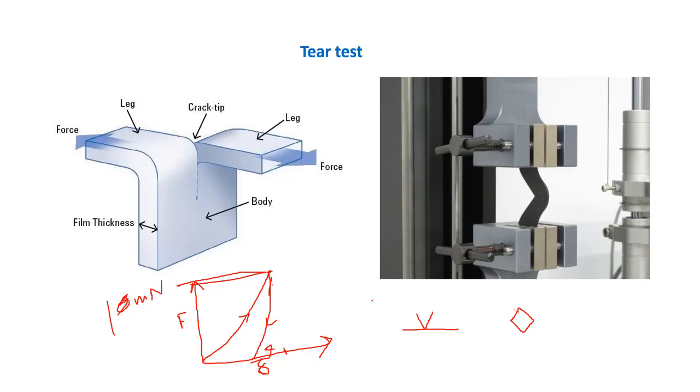It will give me a hardness value, but from this curve I can also get the yield stress and the elastic modulus. So it is related at some point, and we can do that for polymers also. I think you can get the yield stress for polymers using this. Maybe this is the only way. I'm not sure, but with this, we can definitely get the idea.